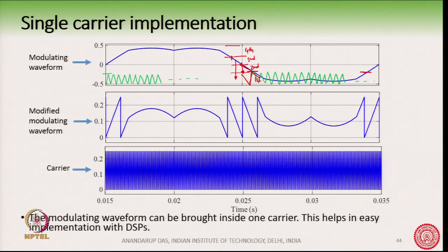Here is the fourth carrier. So, the whole part of this waveform, this part here, will be fully pushed down inside the green one. That is what this push has done. This is the shifted waveform. Okay. So, I have pushed this whole thing down, so that now this is the new modulating waveform, and this modulating waveform will be compared with the carrier like this,